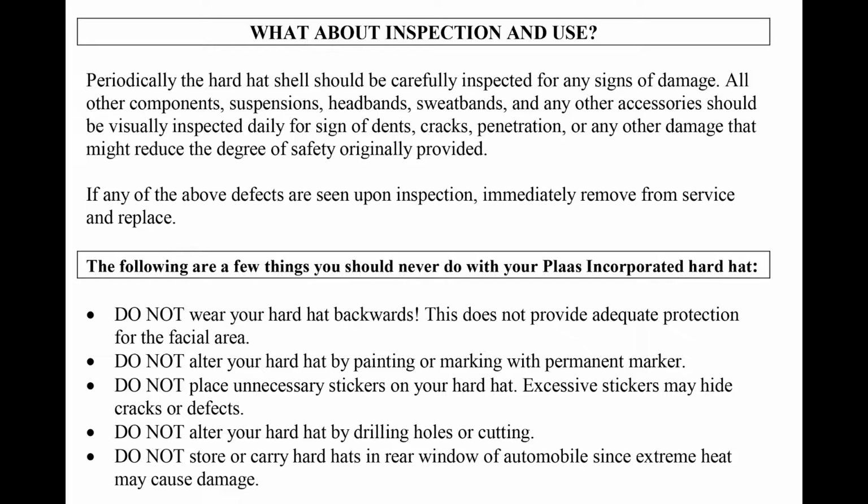Excessive stickers may hide cracks or defects. Do not alter your hard hat by drilling holes or cutting. Do not store or carry hard hats in the rear window of an automobile since extreme heat may cause damage.